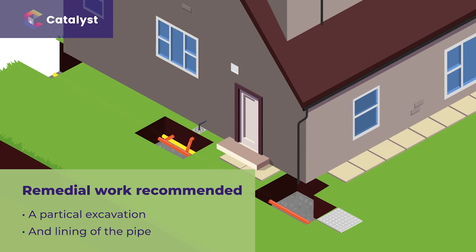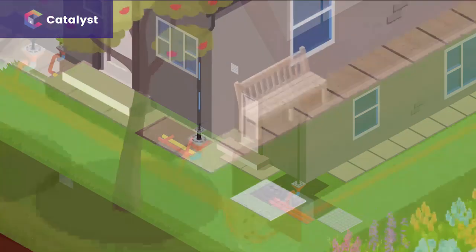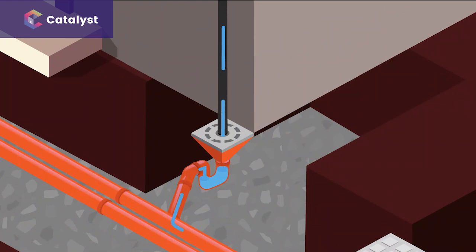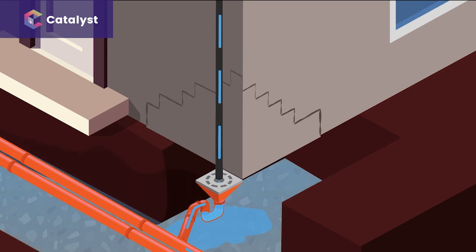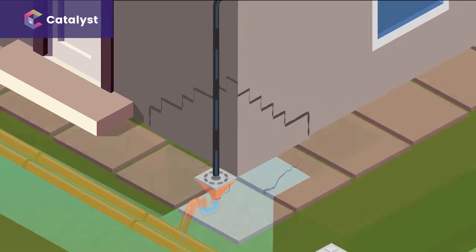the local water company. Rainwater Gully 1 was found to be blocked and water discharging to ground in this area. A water test was carried out and the gully failed. This is within the zone of influence and is possibly contributing to the subsidence.